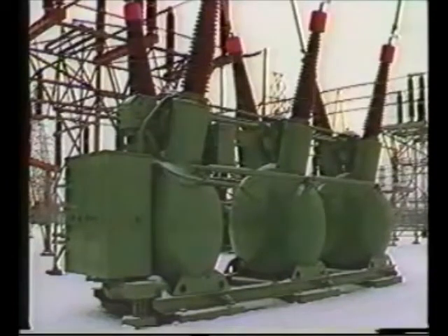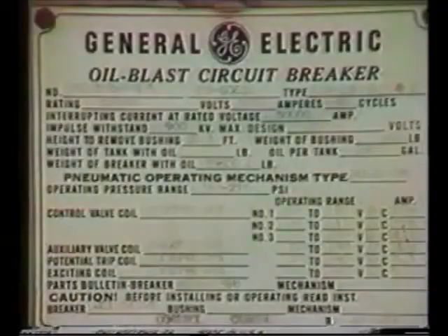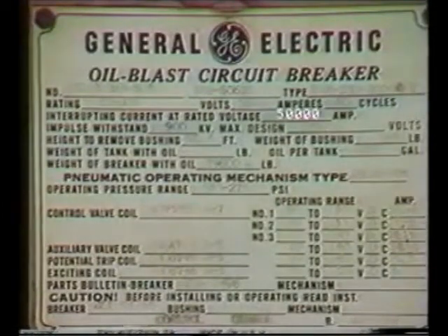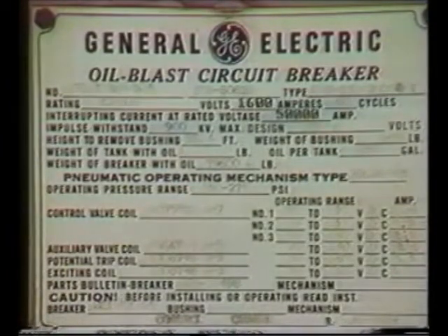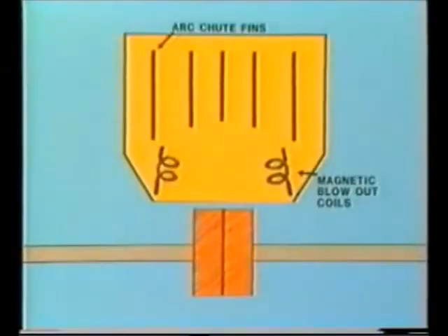Conversely, the circuit breaker would have little value other than as a manual switch if it were not coupled to protective relays. The circuit breaker is specifically designed to interrupt fault current, which may be 10 times or more than normal full load current. It achieves this by breaking the current flow in a specially designed interrupter.